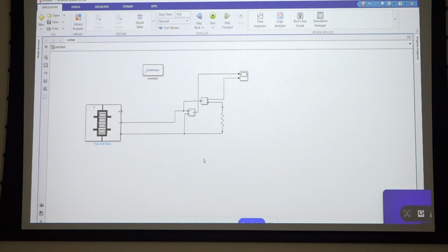And if you only have a mathematical model, that means you don't have any components like IGBT, diode, or transistor, then you can go only with phasor mode. Phasor mode is a little bit quicker. Actually, this provides you RMS analysis.